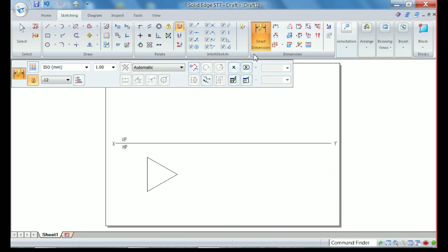So one more thing you should be careful here. Always remember, while solving the problems on projection of plane surfaces, if the plane is resting on one of its edges, then that edge should come left hand side. Either it may be resting on HP or it may be resting on VP. Or the other thing is, if the lamina is resting on one of its corners, then that corner should come left hand side.